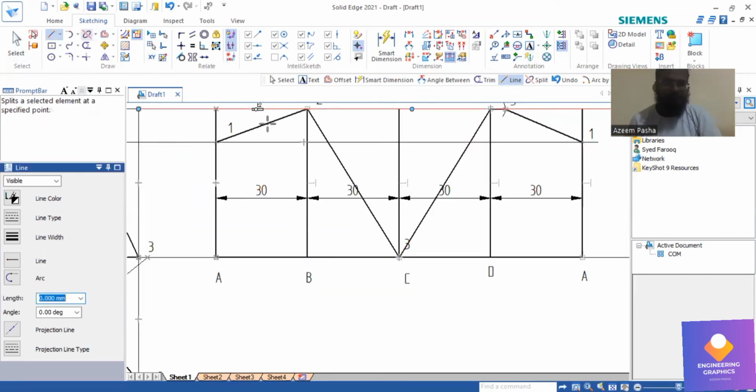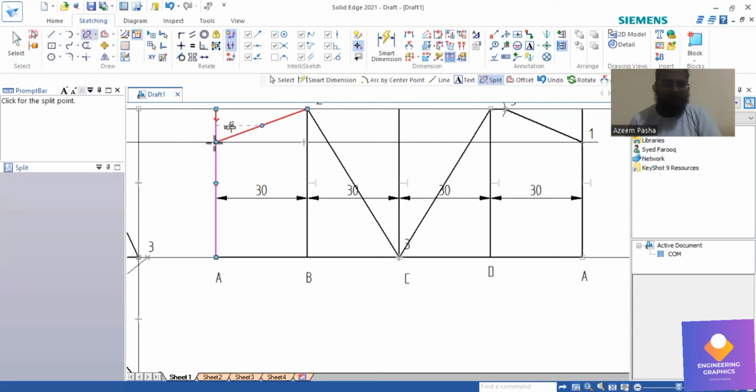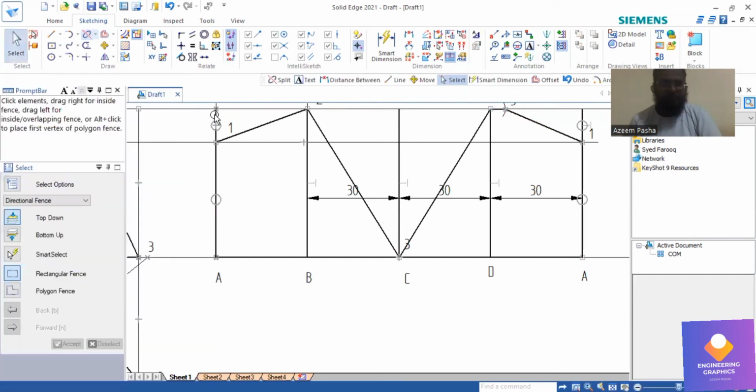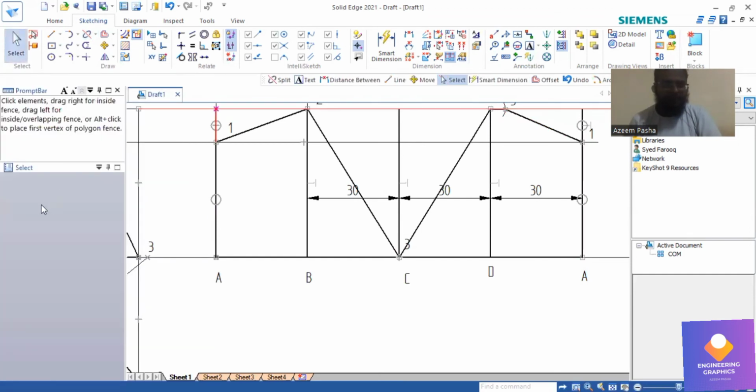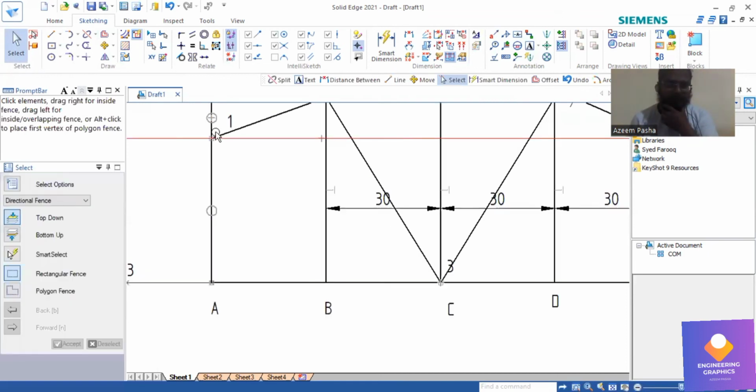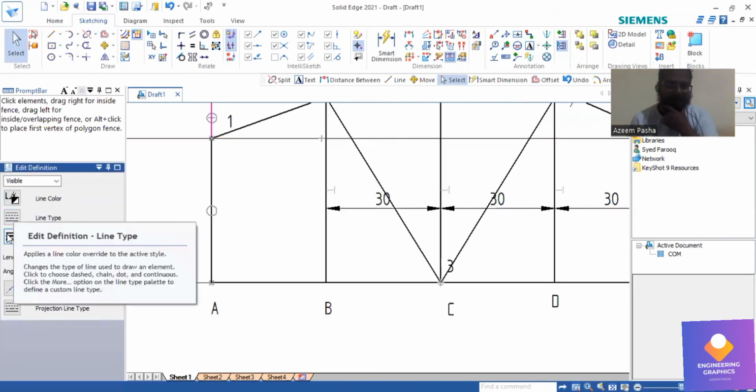So this completes the problem, but you can see, using a script command, I'll be showing only the lines which have to be thick lines. The cut remained portion we have to make thick, and the other part we should make a thin line. I'll be making that a thin line here. Just see that.